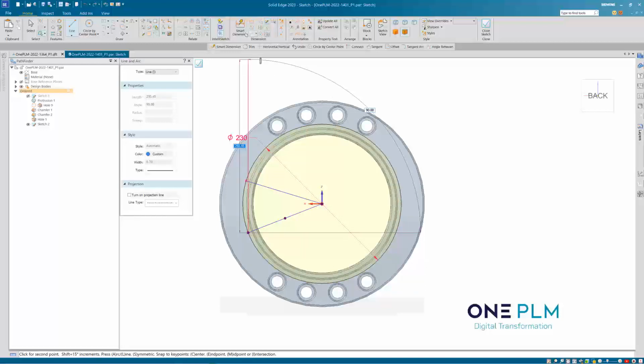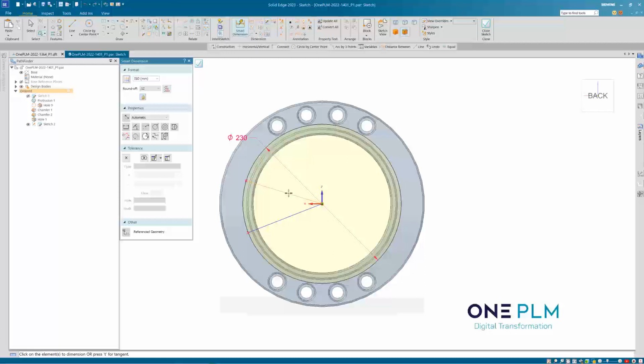here. I want to do a smart dimension between these 2 lines, so I want to do that line, press the A key to get my angle, just tap it, and then do that one. And we're going to have 34 degrees between those 2 on there. And then I want another one. If we just click on a single line and press the A key, that will allow us to create an appropriate dimension on there. So that needs to be 18 degrees down from there.